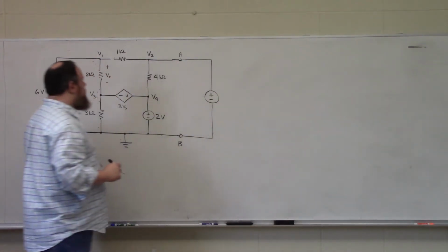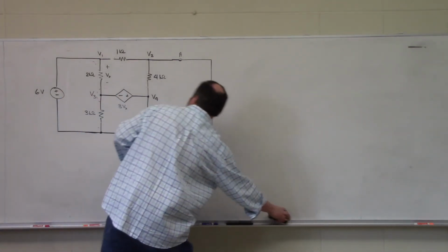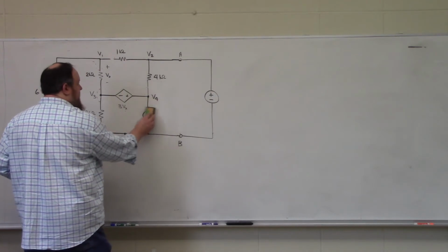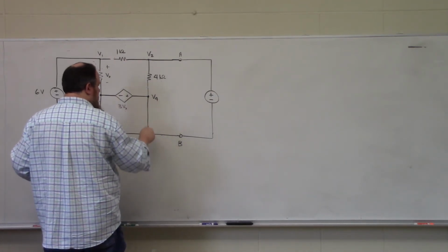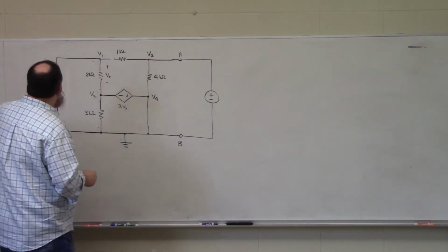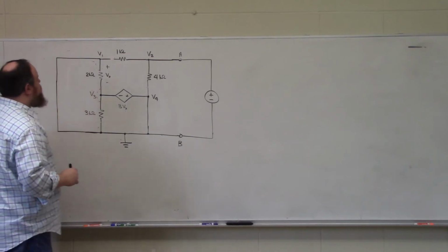So I'm applying a voltage source. We'll discuss what value I should use in a moment. But it's very important that I apply it to a dead network, so I need to turn off all of my independent sources. So I turn off voltage sources by replacing them with short circuits.